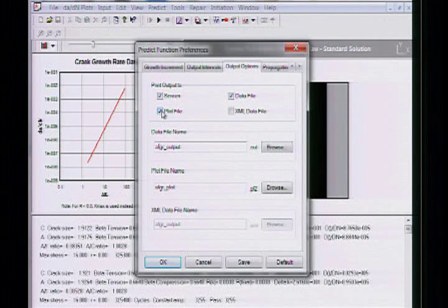In a plot file, you don't want that because you want to maybe bring it to Excel. You don't want to have headers every single line to sort through when you want to plot something. So the plot file is a text file without the headers other than just at the very top. We also have an XML file. If you wanted to print out with tags that we have in AFGROW for different values, then you could use some kind of a template to print out a form, let's say, that you wanted to format in some way. But that's what you have an option of doing also.